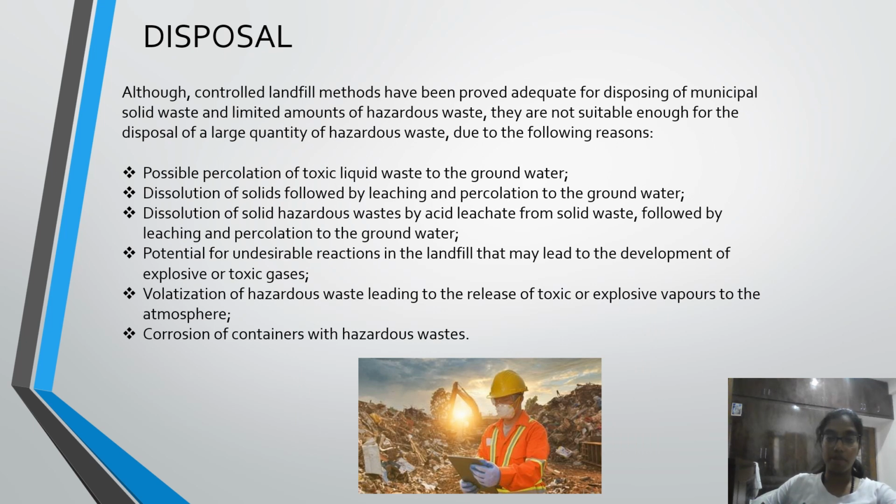Controlled landfill methods have improved for disposing of municipal solid waste and limited amounts of hazardous waste. But a large quantity of hazardous waste cannot be landfilled because of the following reasons. First is possible percolation of toxic liquid waste to the groundwater, which will not be suitable for drinking. The second is dissolution of solids followed by leaching and percolation to the groundwater. Third is dissolution of solid hazardous waste by acid leachate from solid waste followed by leaching and percolation to the groundwater. Fourth is potential for undesirable reactions in the landfill that may lead to the development of explosive or toxic gases, which we breathe and which cause respiratory diseases.